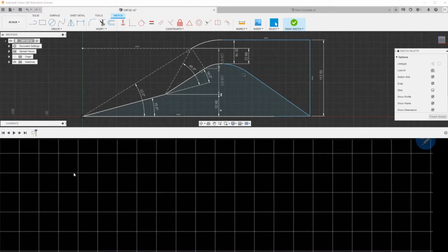Once we have this geometry defined, it's a bit different from what you showed, but the idea is similar. The flow enters with supersonic velocity from infinite distance, with a known Mach number. So you cannot change the mass flow rate of air just by constraining here, because when your diffuser is working optimally, these three shock waves happen.